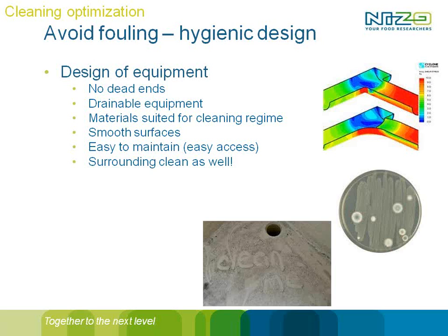For example, if you have a steel which is corroded by your cleaning agent, your surface will become worse. So be careful with the cleaning agents you use, and take care that the materials of your equipment can withstand it.